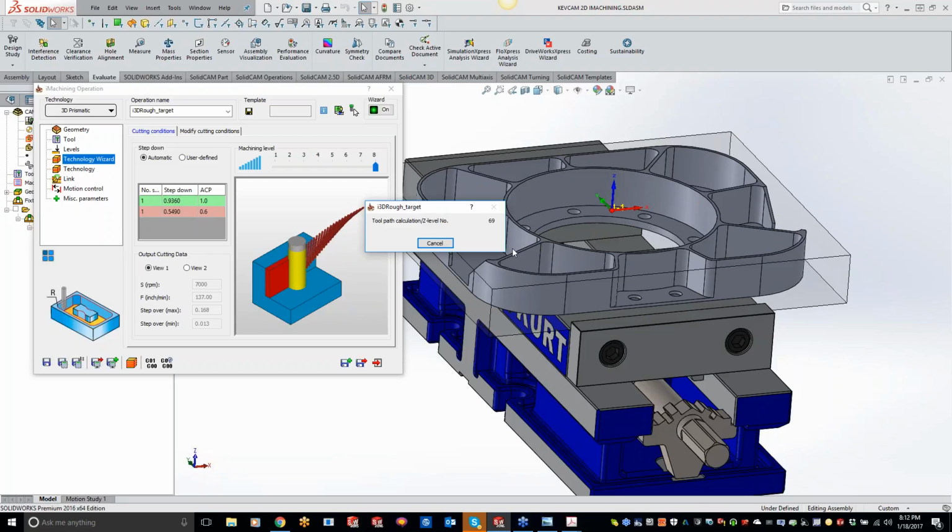Like I said, guys, I know some of this is a bit of a repeat from last week, but when you get into those square corners, you'll get a little bit of chatter, not a nice finish, and a little squeal going on. That's basically because we're over-engaging our end mill. With iMachining, you'll never over-engage the cutter, and once this is done calculating, I'll show you the maximum angle of engagement that we're going to use and the minimum angle of engagement.